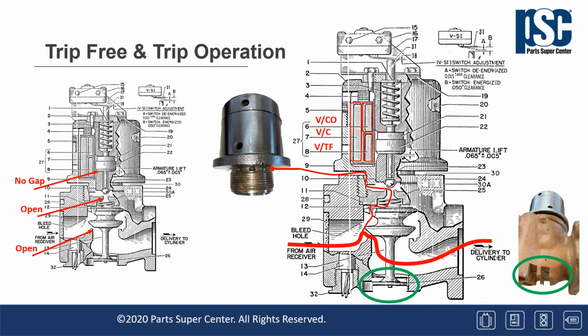So both of these windings will be energized in order to quickly reverse the polarity of that magnetic field that's in the pole piece to allow the pilot armature to drop down and seal off the pilot air circuit so that the piston can close in the control valve and shut off the air supply to the circuit breaker cylinder. This will allow the circuit breaker linkage to collapse so that the circuit breaker can trip free.